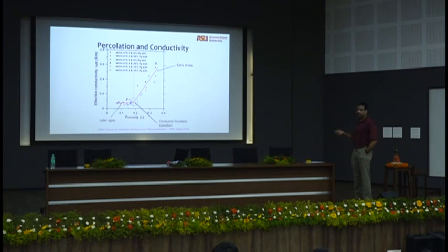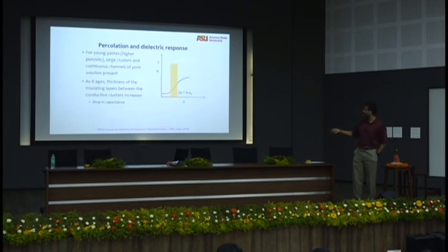Effective electrical conductivity that I measured with a lot of samples, without fly ash, all of that, at different times, because porosity changes with time, right? And I plot that with porosity. You see, I get a trend like this and a trend like that. At what point are they intersecting? And what did I say is the importance of 0.18? That is the level of connectivity of pores that you can afford when all the solids are connected. I showed you that close to 0.2 value in the previous slide, right?